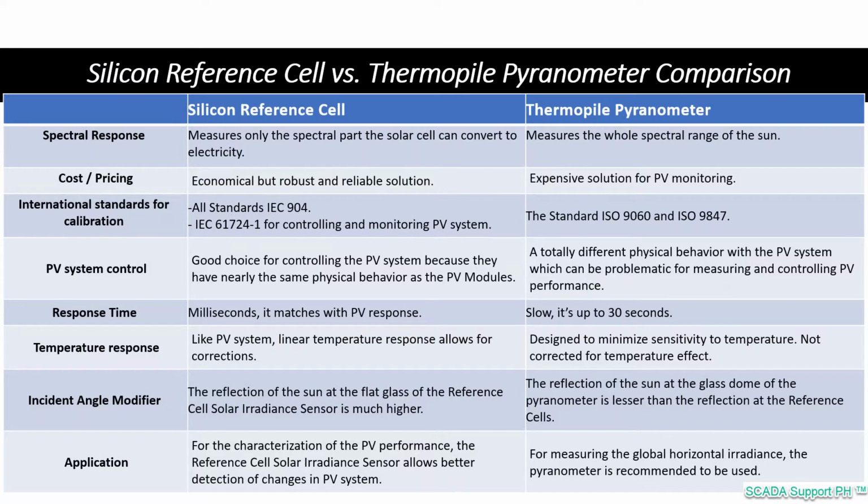Here is a tabular comparison between the silicon-based reference cell on the left and thermopile pyranometers with respect to each category when it comes to implementation, as well as aspects of PV systems performance monitoring.